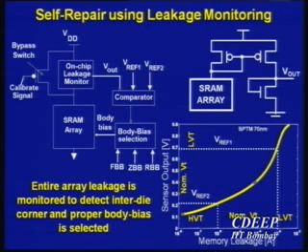And that's exactly what was done in this particular case. I have an on-chip leakage monitor, and this is a very simple-minded current mirror circuitry. On top of that, a comparator, a body bias selector circuit, and so on. So when the leakage is high, I know that I'm in the low VT corner, and basically take corrective action by applying the proper body bias.